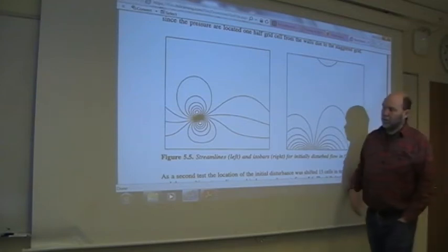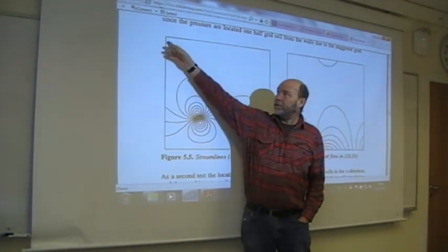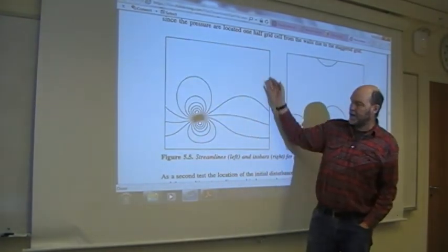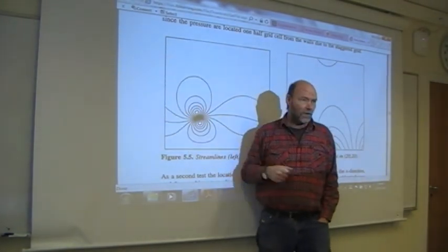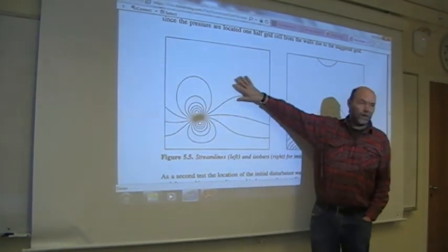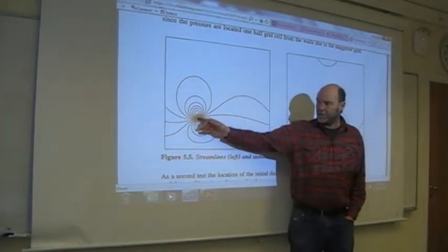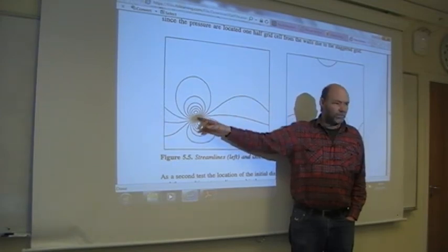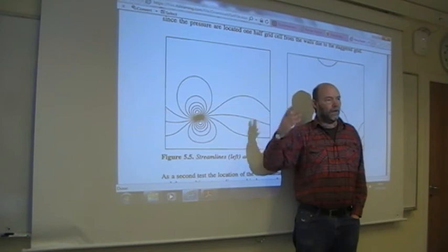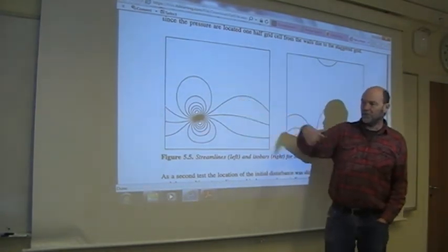So I start out with an open area, and I have periodic boundary conditions in the x direction. So whatever goes out here should come in here. And then I start, initially everything equal to 0. And then I create just a noise. I just set up one velocity here, one u and one v. And then I do a couple of iterations, finding a solution here, or just some time steps.